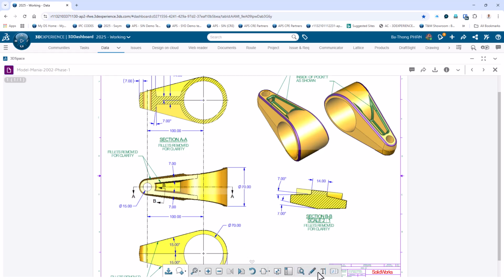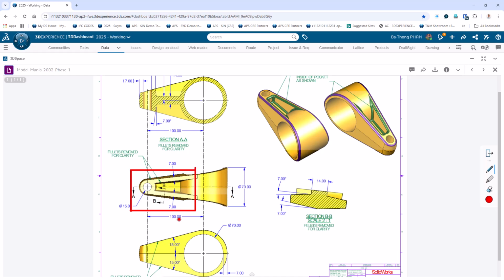That is the thickness of the wall on top after applying the draft angle, and that is 7 millimeters from the top edge on a plane that is likely inclined by 15 degrees. So that face is 15 degrees to the horizontal, and we need to respect the 7 millimeters from the outside edge. That is the very tricky one.